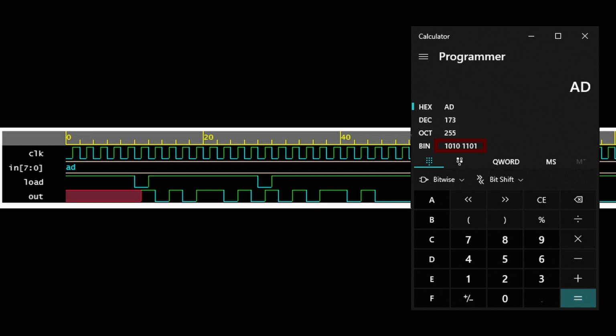You can see here that when the load pin goes low, it loads the AD, and then on the next positive clock cycles, it outputs the 1010 and then 1101. Imagine if that is then an input to the color PROM chip. It would be the line pattern of a character in the ROM. The chip doesn't carry on outputting if it's worked through its bits and doesn't have a new set loaded.